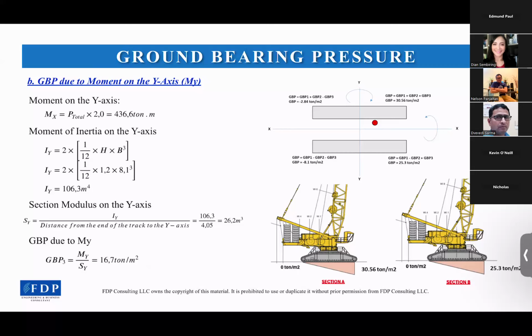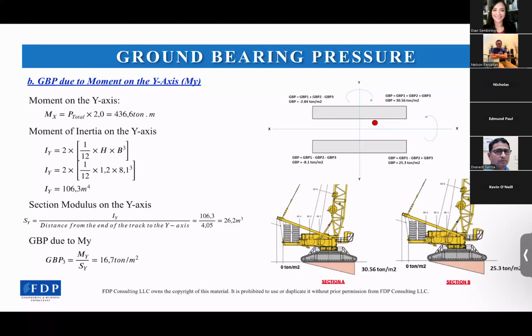Sure, Paul, that's a critical one before doing any lifting plan. We need to know the ground bearing pressure, so we could design as per the capacity.